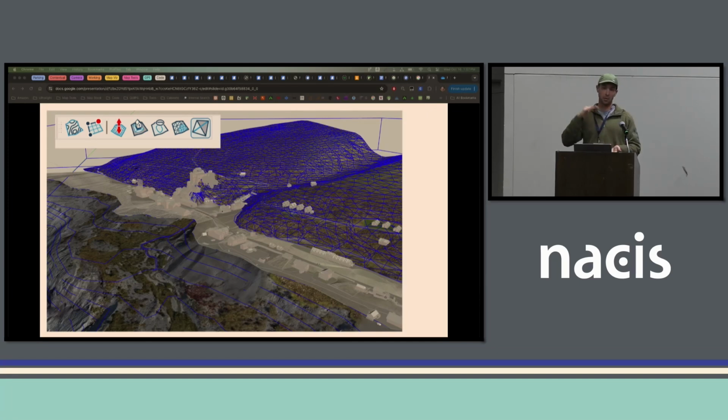So now I can position all the buildings how I want, I can grade them to the appropriate grades, and then I can combine it all into the actual terrain model that you see to the west and the east of this. And some of the buildings, like the little houses that you see in the blue area, you just go ahead and lay those in the terrain. They're not part of the core workflow here.